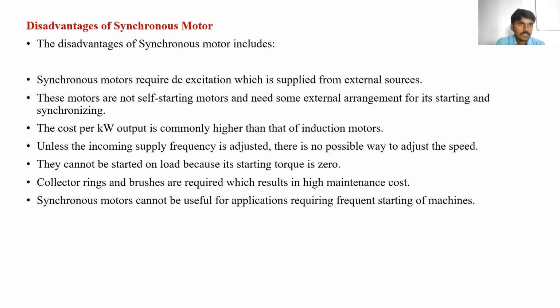So what are the disadvantages? The disadvantage of the synchronous motors includes that it requires DC excitation, which is supplied from external sources. In the case of the induction motor, we only need to give supply to the stator.